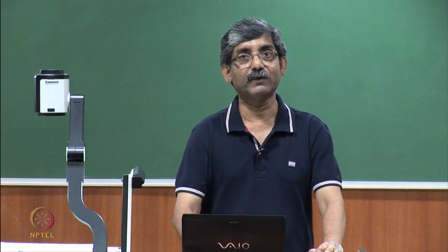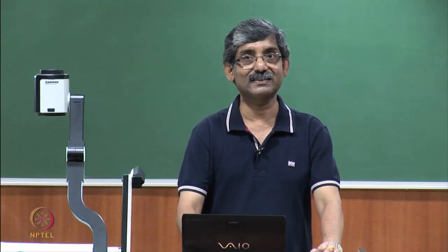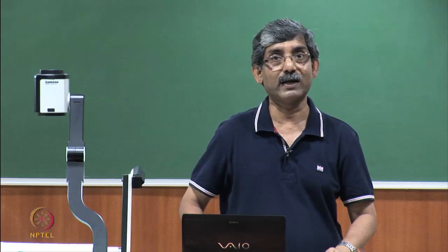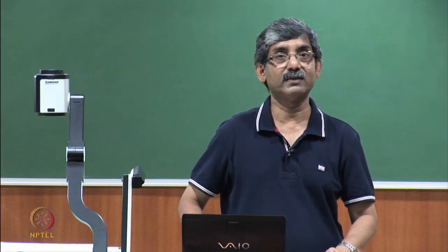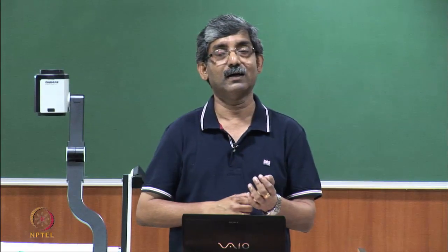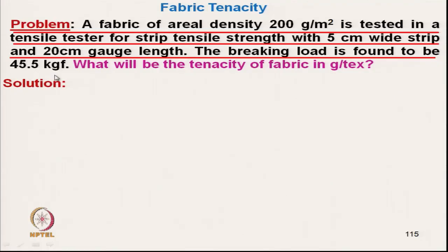So, a fabric of areal density 200 gram per square meter is tested in a tensile tester, that is strip tester, with 5 centimeter wide strip and 20 centimeter gauge length. Okay. So, the data we have taken, it is a simple calculation. The breaking load is found to be 45.5 kgf. What will be the tenacity of fabric in gram per tex?